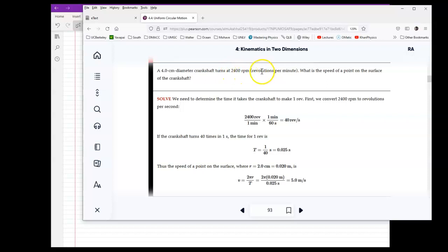Now, when we say RPM is the revolution per minute, what is that? Well, you can think of it as the frequency, but in minutes. Remember, when we talk about frequency, we say revolution per second. And by the way, it has a unit called hertz specifically for that. Revolution per second is also hertz. So this is also frequency, but it's in the wrong unit. Keep that in mind. When we talk about frequency, it's always per second, not per minute. So you must convert to second.